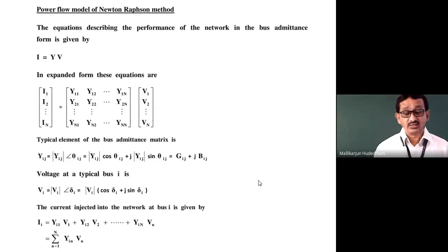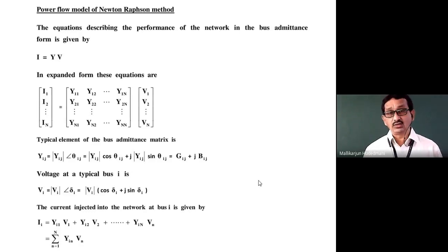There is another method which we call the Newton-Raphson method, which is a very powerful tool to solve such nonlinear equations of the mathematical domain, as well as our electrical problem, as the load flow equations which are created are very non-linear in concept. To solve them, we prefer the Newton-Raphson method as well.